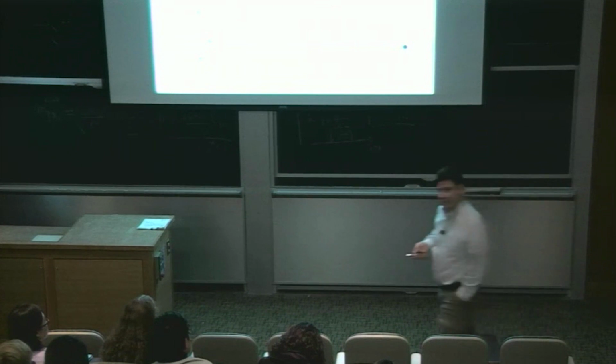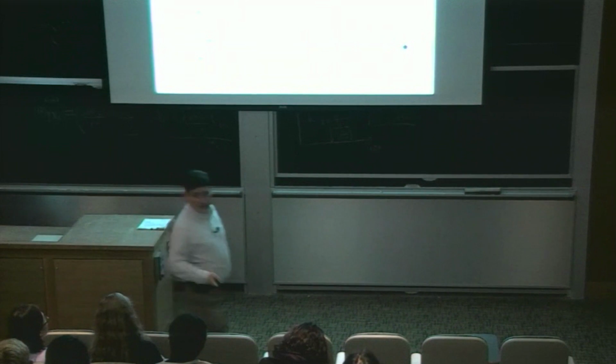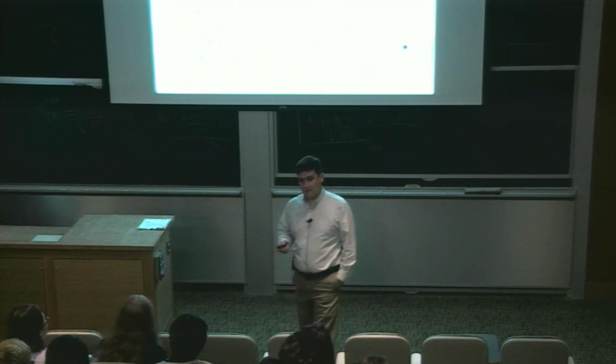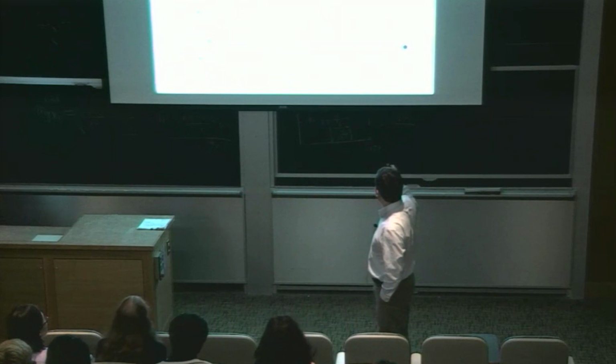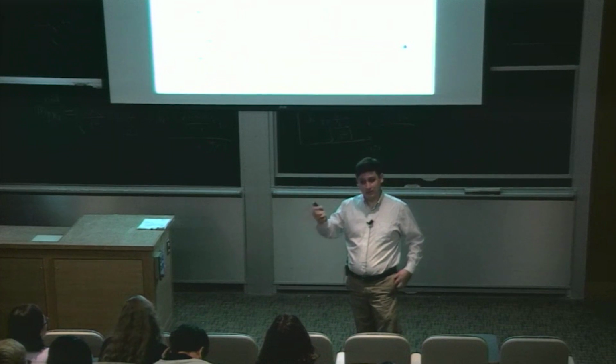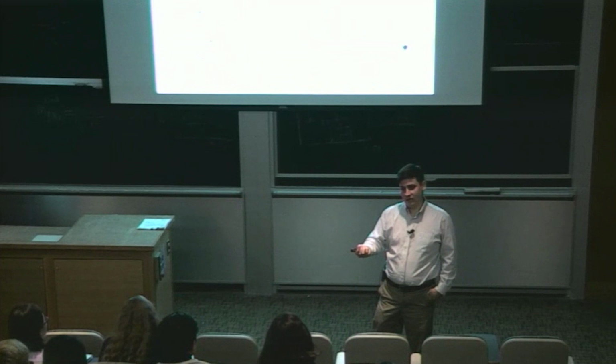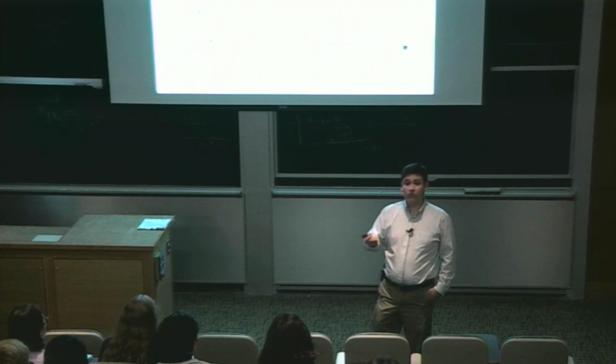Is there a reason here that Newton-Raphson is the default? Good question. Eventually we're going to get close enough to the solution that all these steps are going to live inside the trust region ring. It's going to require very small steps to converge to the solution. And which of these two methods is going to converge faster? Newton-Raphson.